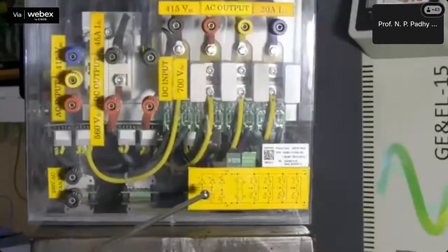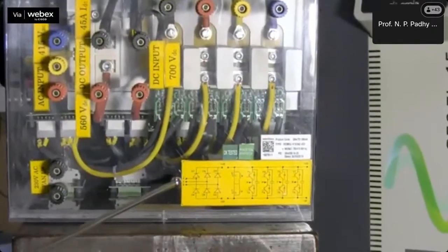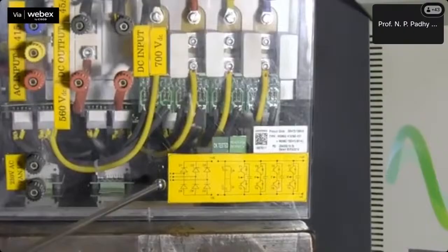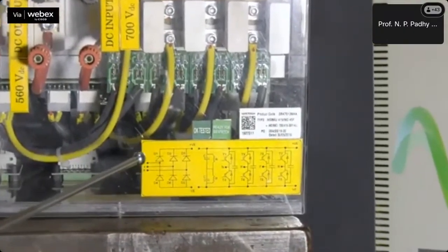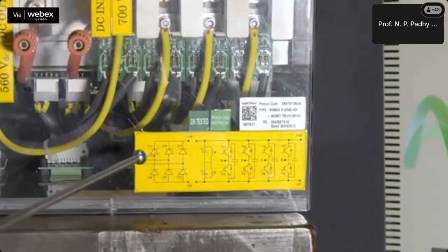The grid emulator is connected to an MCB, which is the point where the inverter is connected through an inductor. In this grid-integrated DC microgrid hardware test bed, the AC bus voltage is set at 110 volt RMS with 50 hertz frequency. Semikron IGBT stack, we can see here in the video, we have shown a single IGBT stack which has Semikron switches and diodes.